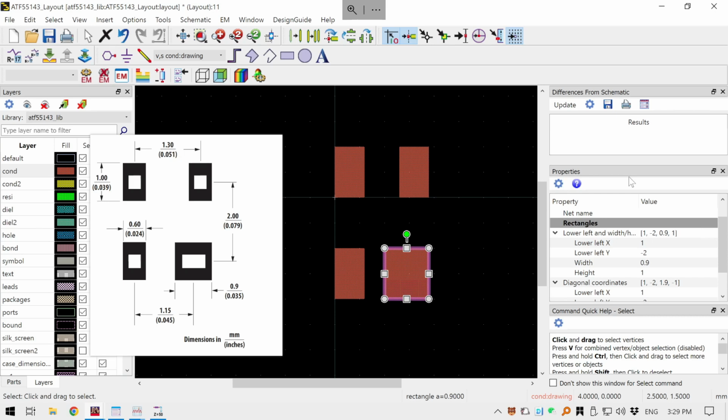Yeah. Once we have these 4 pads, now we are creating the ports for it. We see that the amplifier has 4 ports, but in the layout we need to assign 8 ports actually. So we have 4 ports to connect the amplifier, and another 4 ports at the edges of the pad so that we can connect the microstrip lines. Okay, so the way we're doing this is